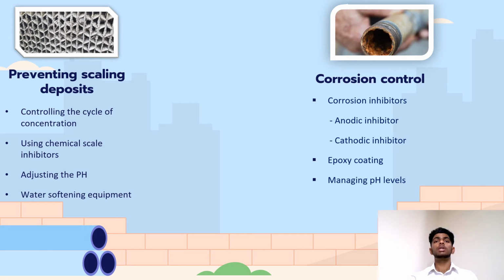and then the cathodic inhibitors are effective by the formation of a protective inhibitor film at cathodic corrosion sites to prevent oxygen reduction. It is more effective than anodic inhibitors and a lower dosage level is required. The types of cathodic corrosion inhibitors are polyphosphate, polysilicate, zinc, and polyphosphonates.